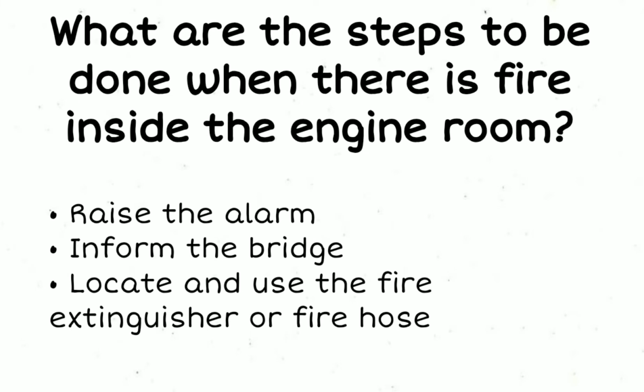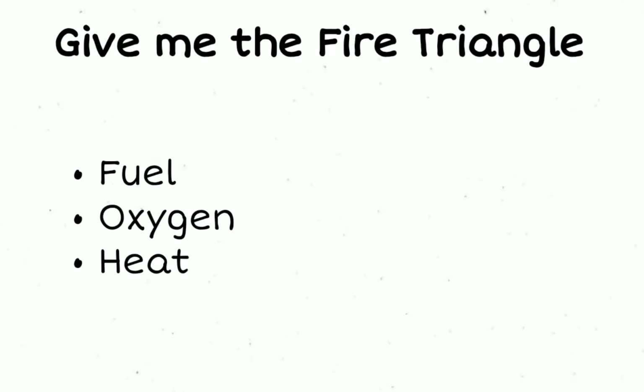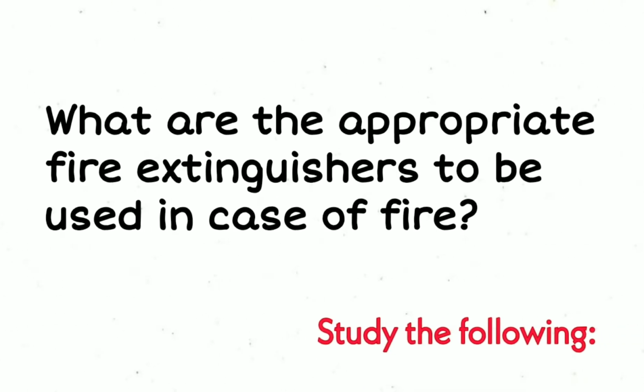What are the steps to be done when there is fire inside the engine room? First is raise the alarm. Inform the bridge. Locate and use the fire extinguisher or fire hose. Give me the fire triangle. Fuel, oxygen, and heat. What are the appropriate fire extinguishers to be used in case of fire? Study the following.